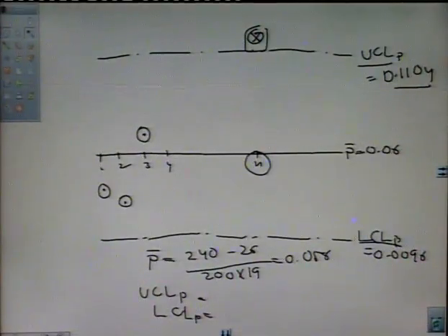So without this particular value of 11th sample, we are going to again plot, and if all the points lie within the control limits, then only these control limits will be categorized as the final control limits of the P chart. So this is one example of the P chart. Then for the example of control chart for defects, we take another example.